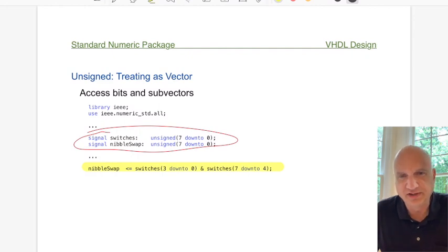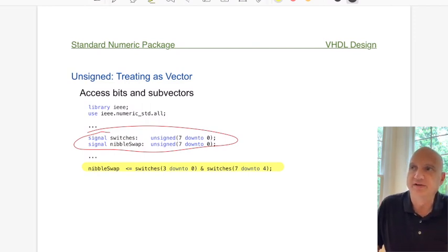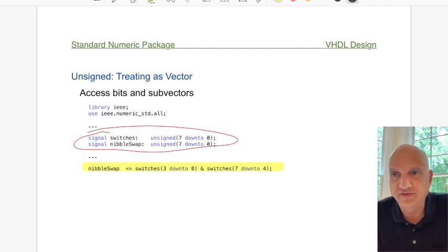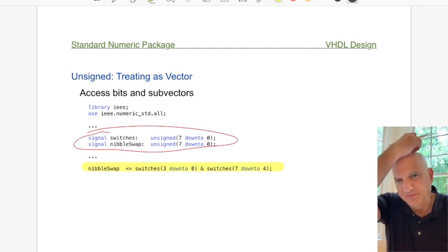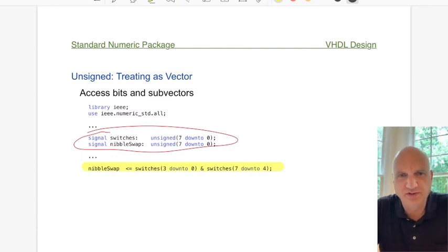especially when you consider that using an integer can be an incredibly beneficial part of a VHDL design, because it doesn't really limit you to the number of bits. You don't even need to worry about it. Let's say you have a series of data that you want to read in, and there's 532 bytes worth of data for whatever reason, and you want to create a way to count through that. Well, you could try to compute how many bits that would be, and then how big a vector you would need, or you just declare an integer that goes from 0 to 532 or whatever the number was, and that will cover it for you.